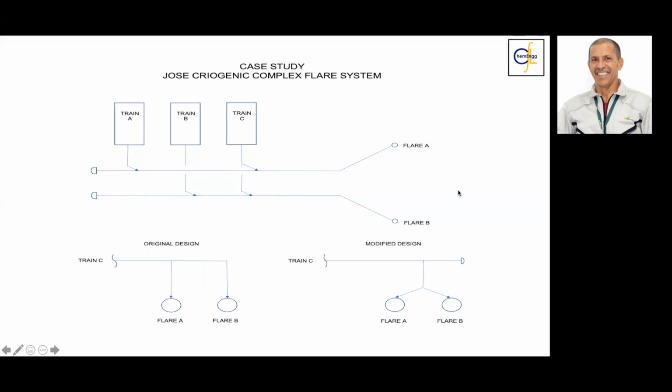Okay, and then most of the time you go for a flare with a higher capacity than the flow rate that is required to be relieved from your safety valves and the depressurized system. Okay, and this is the gap that you have to play with in the flare capacity, and then you can see how many flares can be installed in that case.